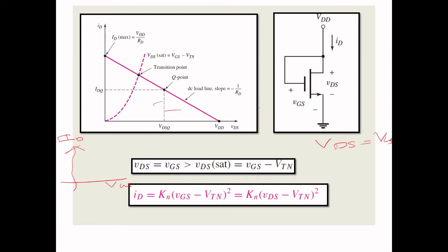So it is an enhancement MOSFET, right? In the enhancement MOSFET, you want to give a minimum amount of voltage to create the channel. Until that, the channel will not be created and the current is also zero, right? So that we are taking as a threshold voltage, right?